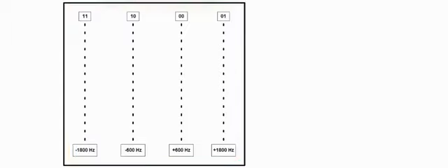Modulation fidelity is an indication of the quality of the signal being transmitted by the radio. The EIA-TIA 102 P25 standard defines modulation fidelity as the degree of closeness to which the modulation follows the desired theoretical modulation. Rather than being just one measurement, modulation fidelity is a combination of a number of parameters including frequency error, symbol deviation, and RMS deviation error.